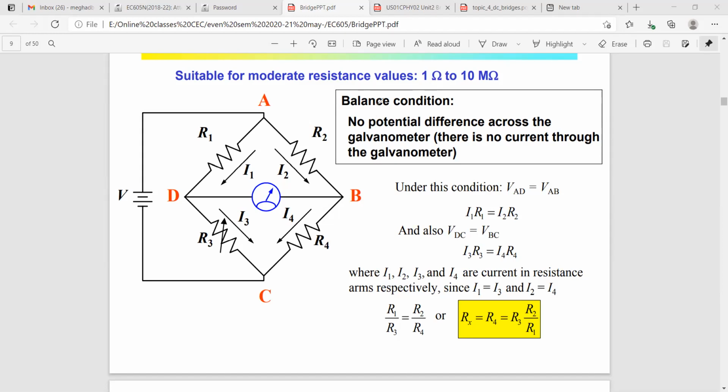Yes, ma'am. So this is the thing you have to follow, which is the variable. Wherever there is a Wheatstone bridge problem, if you see an arrow on any of the resistances, understand that the arrow is for the variable resistance. Then the formula will change, but the whole process is the same. There is no difference in the process. So this is the variation. One problem I will give you for your homework. Then we will move on to the next thing.